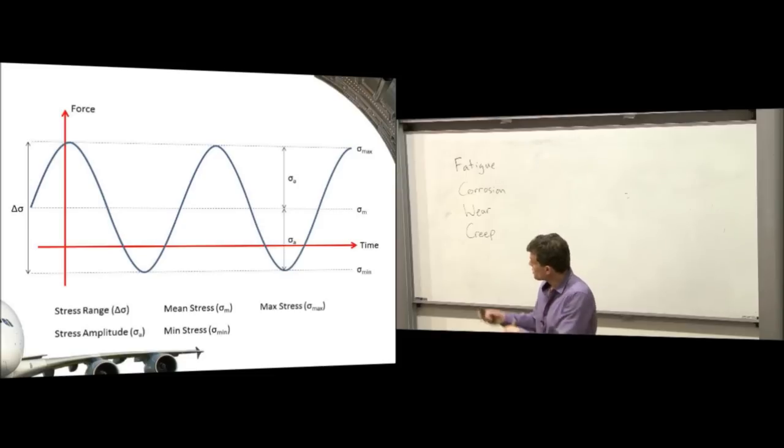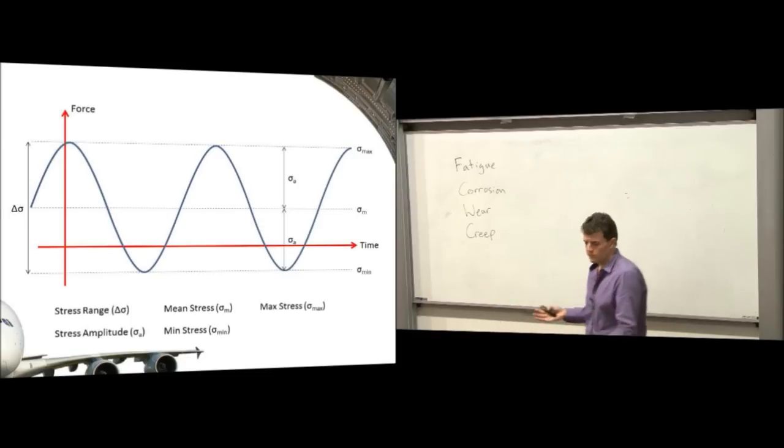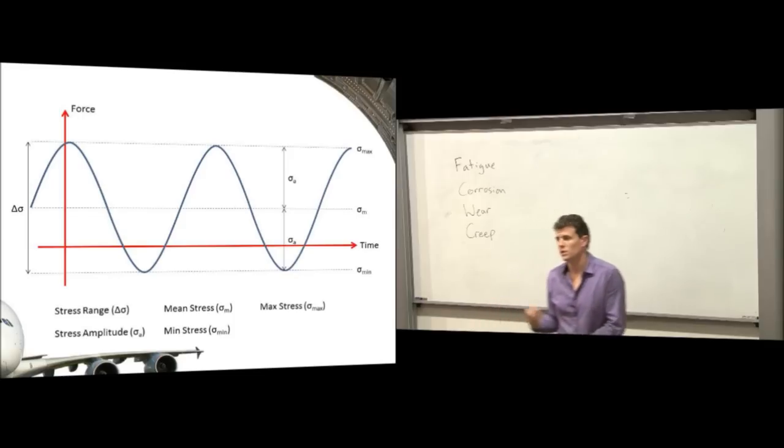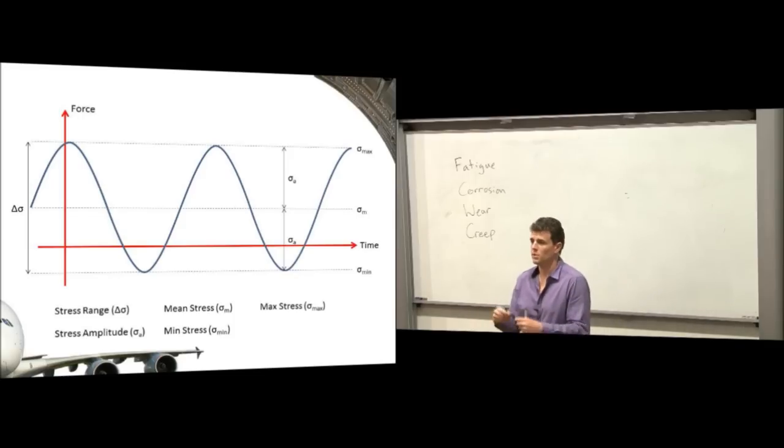Okay, so this is a simple fatigue problem. If we had force being applied to a component, or stress, it should probably be stress up there, and time, we can, in a simple sinusoidal case, like you've done in 2400, take a bar, put it in a rotating machine with a bending moment applied to it.